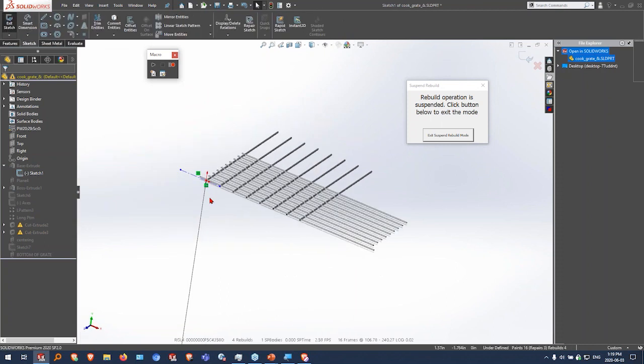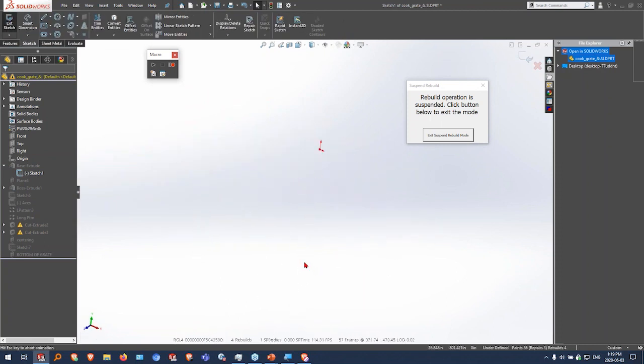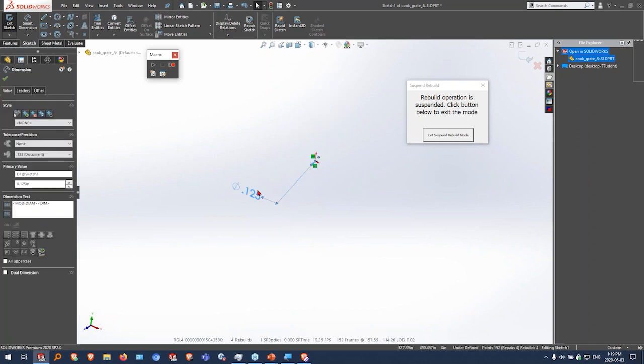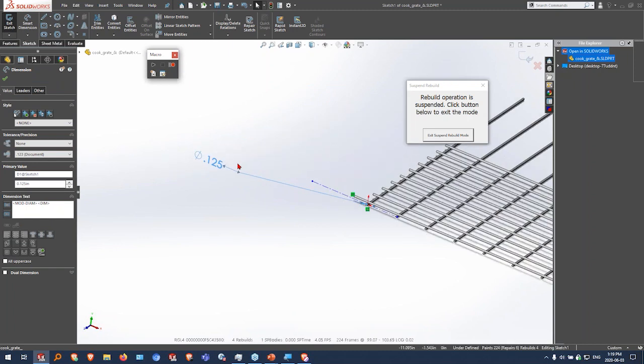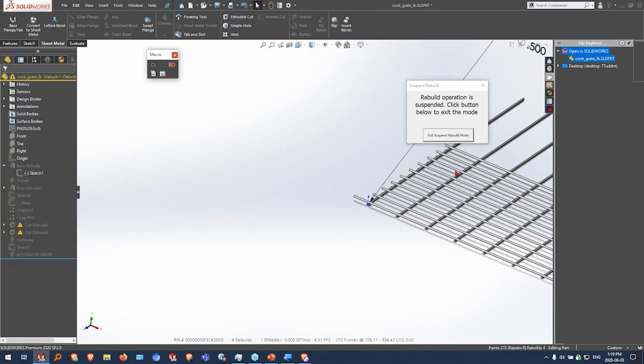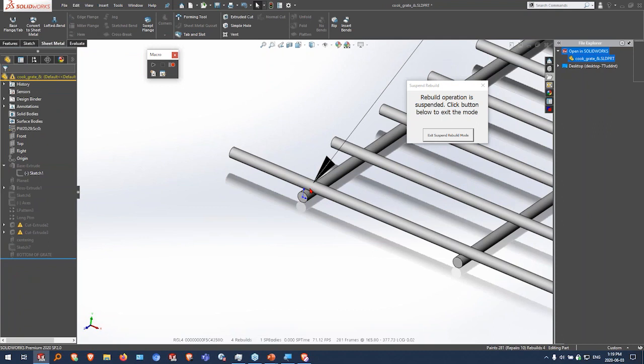So another example is I have this sketch within here. My dimension's really far away, jeez. Okay, so let's say, for example, I got this 0.125 right within here. And now I want to make this, let's say it's too small, and I'll make this larger here. So I'll make this now 0.5. You see the sketch size here update. I'm now going to exit out of my sketch. But you'll notice here the diameter hasn't actually changed at all, right?